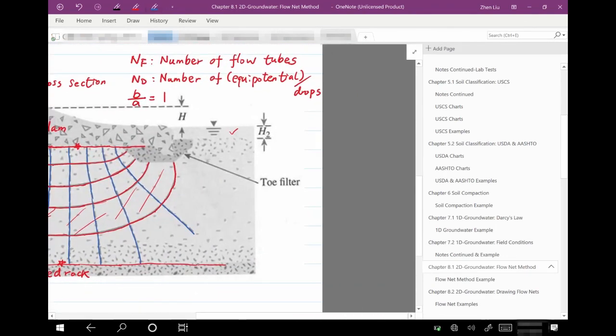On the right-hand side, we have the same thing. So we have another equipotential line here, because every point on this line should have the same water head. Actually, this one will also be the same. This is also an equipotential line because it's connected to this line. And we use very coarse gravel, so the pores are pretty big. We assume that it will not consume water head for water moving through this material. So that's why we assume they have the same potential. There's no head loss.